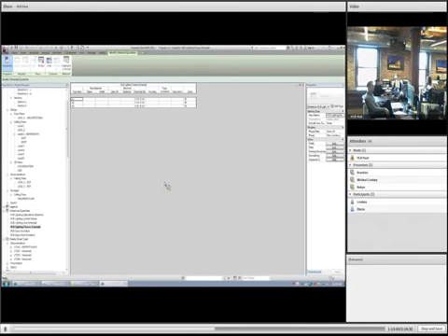Okay. Are there any things that we would need to go into the lighting families to really do? Absolutely. The IES file, that would need to be done. That's specific to each family and requires you going outside of the project that you're working in or the template that you're working in. It requires you going into each one. It's more time consuming and a little harder.